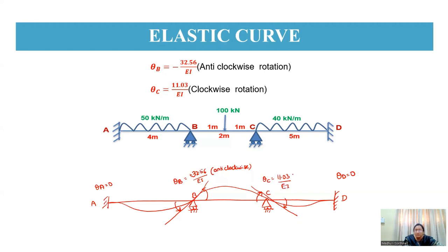Here EI also you can substitute, but I'm not substituting it, so that we can simplify it. It will just get cancelled in the slope deflection equations. That is the reason I am leaving EI here. So this is how you are going to draw your elastic curve.